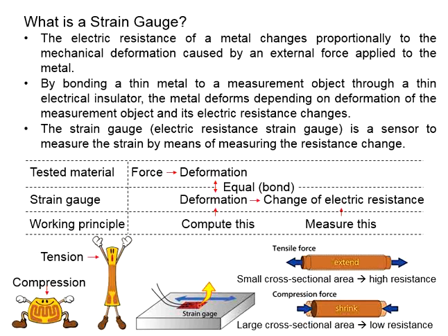not disturbed. Therefore, these wires or electric foil shall be laid on a thin layer of electrical insulator, and this electrical insulator shall be pasted onto the materials that you intend to measure. Place the strain gauge in the right locations to measure the regional deformations. You cannot allow direct contact between the electric foil or the wire with the material.